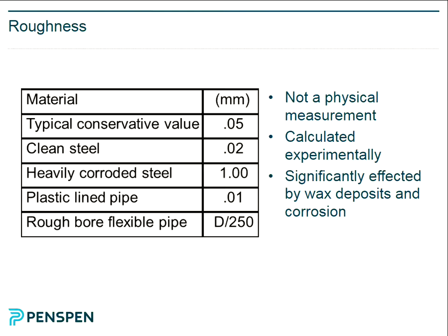So moving on to multi-phase flow now. So that's single phase flow: we talked about the Darcy equation, Colebrook-White, roughness, friction factor, Moody diagram. Just to recap, really, the phase envelope, we're talking about in here, basically, multi-phase flow. Just a quick word about dense phase. Dense phase, as you'll probably remember, is up here, at such a significant pressure that temperature won't affect it, you won't get any liquid dropout.